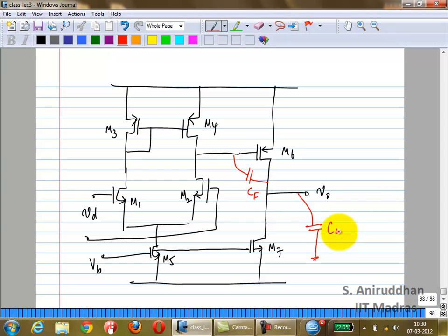Now you want to add a series resistance which is proportional to 1 over GM2. So what would you do? Let's look at the case where you want to add a resistance. Sorry, you want to create a resistance which is 1 over GM2. How would you do that? Using a MOS transistor seems to make sense. You're trying to get something which is GM2. So let's start off by adding a real MOS transistor.